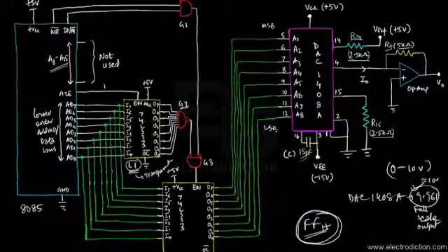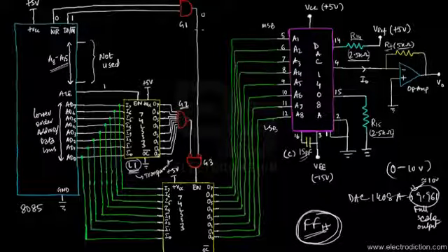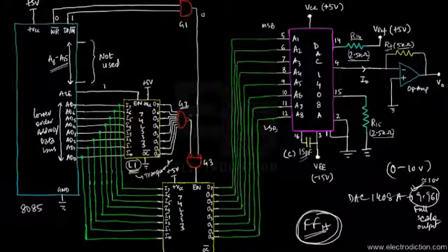After that, since it's an output operation, the 8085's input output memory bar pin would output a logic 1 voltage level. And since it's a write operation, we need to send the data, so the write bar pin would go to logic 0 level in order to enable the process. With these inputs, the gate G1 would have a logic 0 output voltage, fed into one of the inputs of G3. With the address FFH appearing at the input of the gate G2, which is a NAND gate, all the bits at the input of G2 are logic 1, so G2 would output a logic 0 voltage level as well. So both logic zeros go into the gate G3. Now you can see that the input of the gate G3 is an active low input, so the gate G3 is active low in nature.